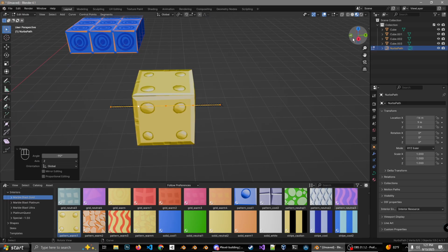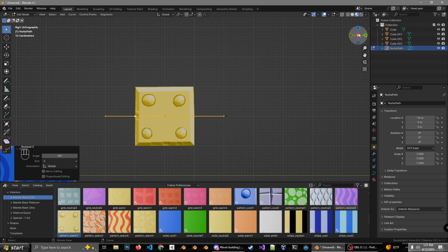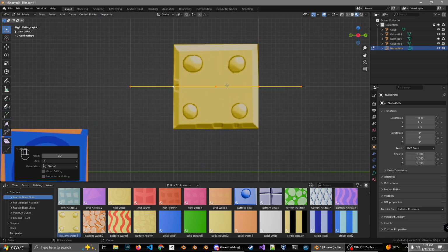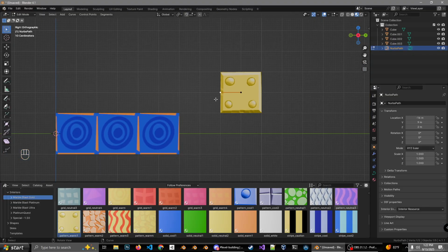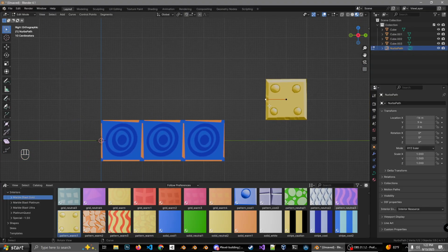And let's go into orthographic view on the X-axis, so you can press numpad 3 or click this, doesn't really matter. Press G, and then let's lock it on the Y-axis and hold Control. And let's make sure the first vertex is lined up with the middle of the moving platform, so that looks good. And we're gonna delete all of these vertices, and we can just leave this one here since we're gonna use it anyway. So these vertices are considered markers in game.